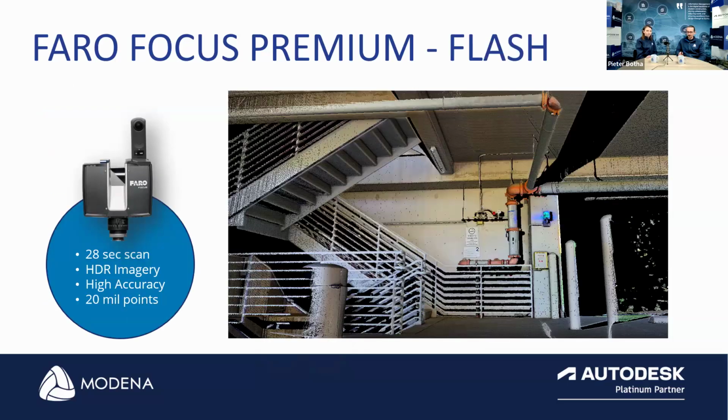Victor, we just had a question over there. It's asking about the accuracy of various 3D scanning technologies like Faro or Matterport. Do you just want to mention the Matterport accuracies as well? Yeah, so the Matterport does also have a LiDAR sensor like the Faro Focus scanner has, where the Focus scanner scans at 1 millimeter accuracy, and the accuracy on Matterport is 10 to 20 millimeters. 10 to 20 millimeters, yes.